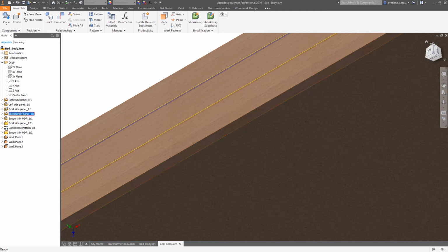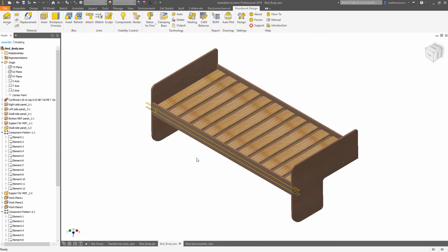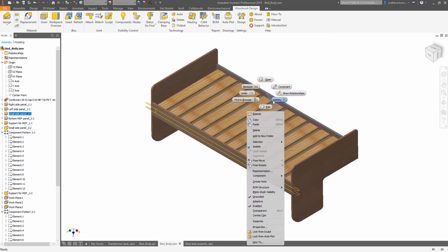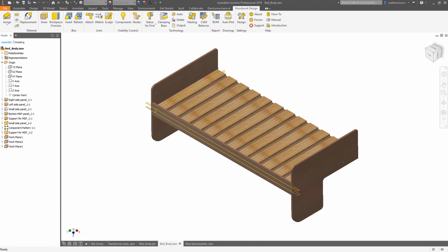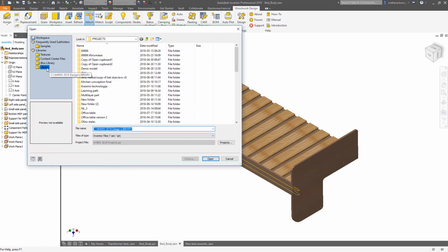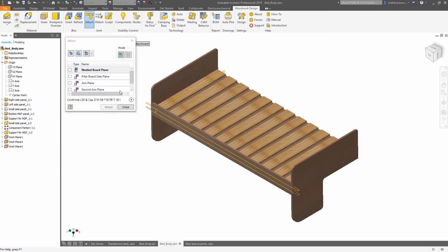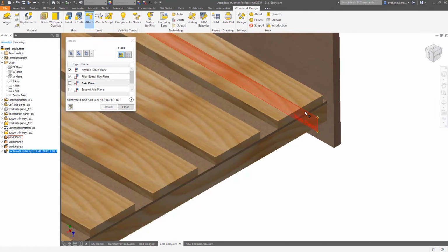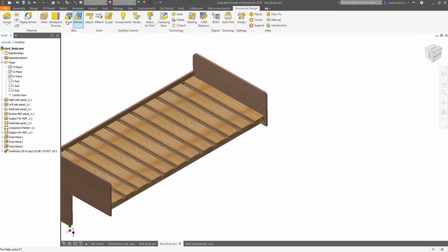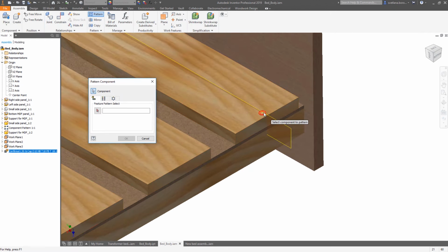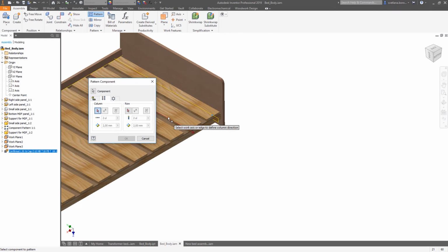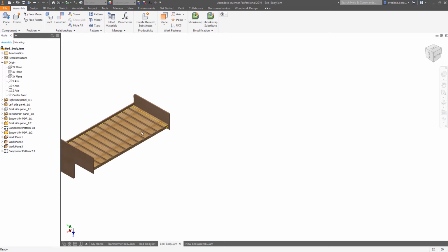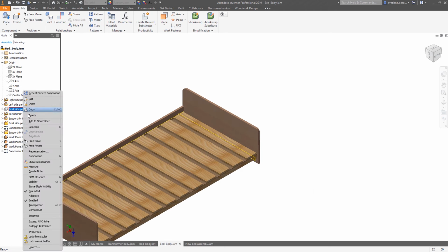The usage of the work planes makes the hardware set very flexible, so you can basically deal with any situation you can face in a real scenario. There is no limitation, just add the reference geometry in the place you need, and then you can use it for your hardware positioning. So in this case, we will use confirmats. Again, they will not be visible because of the mattress, which will lie on top of all that structure. So that's why the confirmats will be used here.